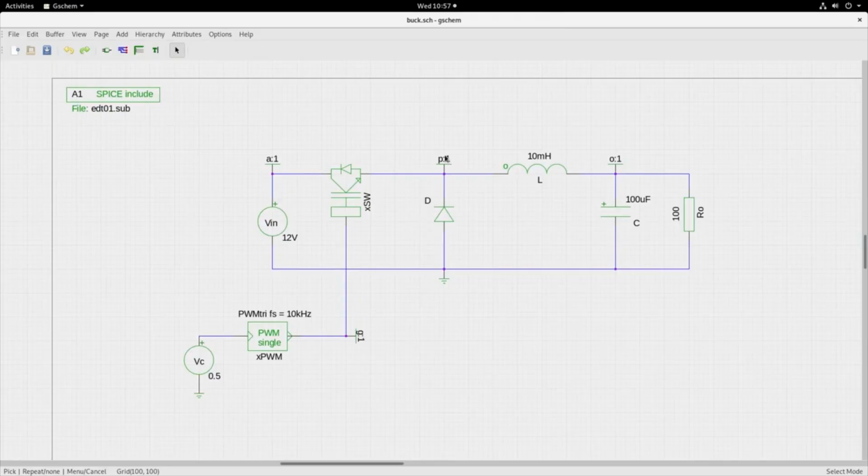So let me see the potential here, Vp. This should be switched, and together with it I will see also the inductor current. We saw the inductor current was of the order of around 90 milliamps or so, and this potential will be of the order of 12 volts, going from 12 to 0. So if you want to see these two waveforms together, this potential waveform and the inductor current, I will scale the inductor current 100 times and then show it on the display.